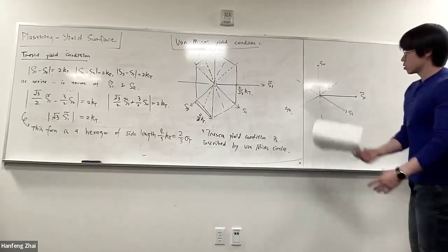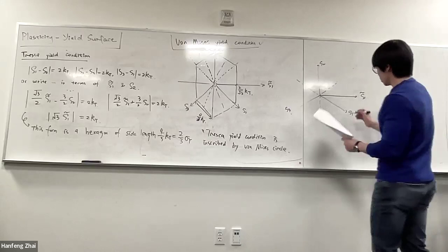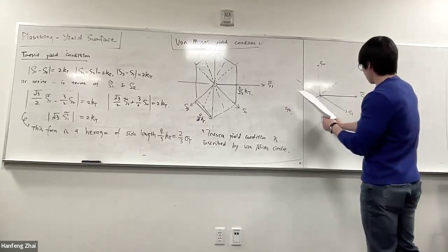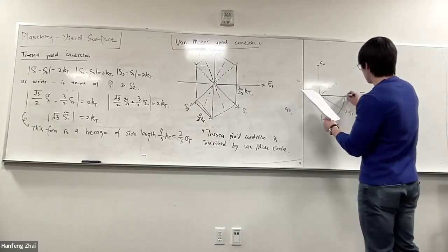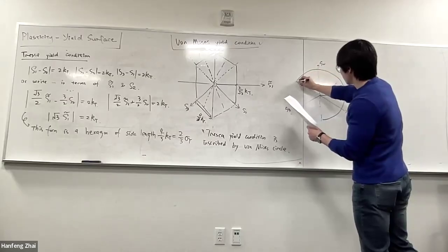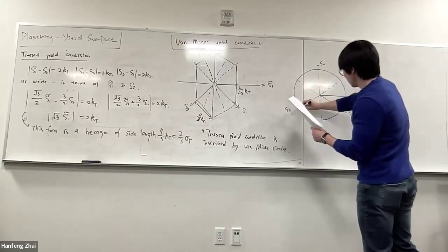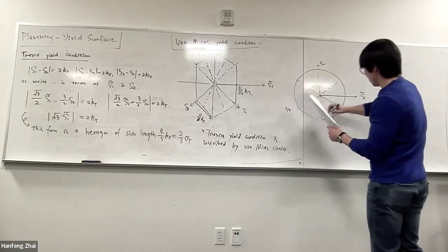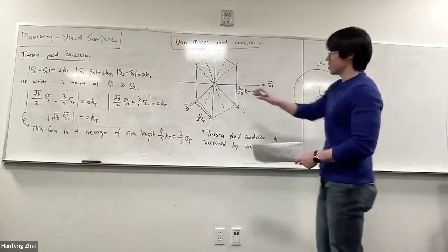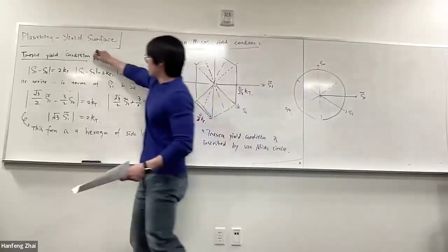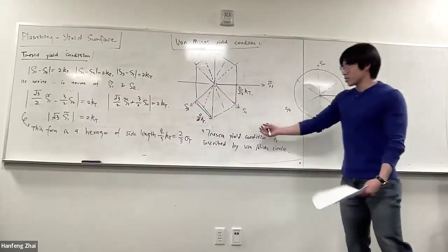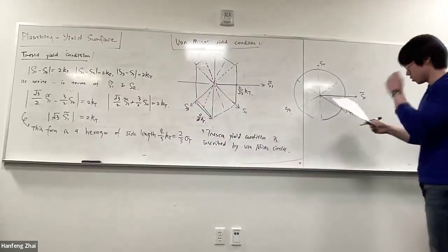What does a von Mises yield criteria look like? Because you recall, in a previous part of this video, it looks like a circle, circular shaped yield surface. I can draw this nice, beautiful circle. Look at that. Wow. Okay. And what does the Tresca condition or yield criteria look like? Because I already told you it's inscribed by the circle.